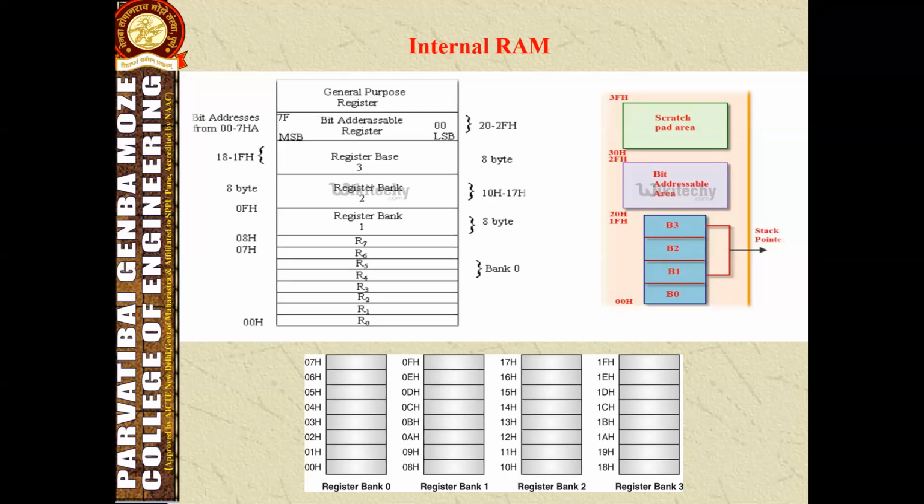If we use bank 1, a conflict will happen because the same memory is used for the stack and as our working area. We cannot use it like this, since bank 1 is generally used for the stack.